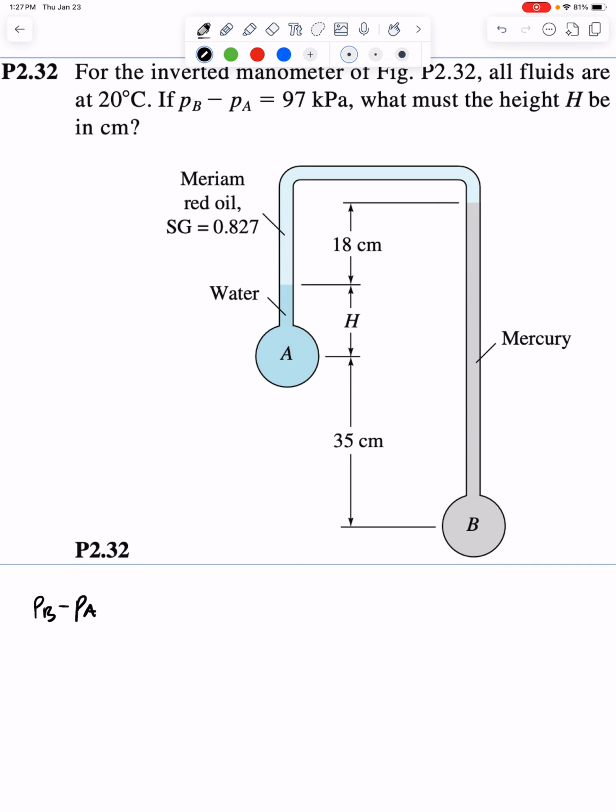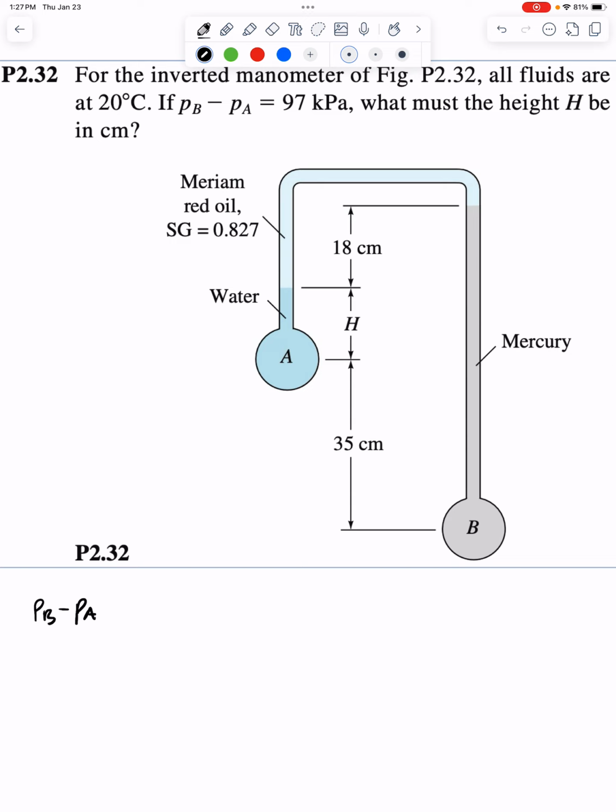So therefore, we got to change the way we think. When we do final minus initial, moving upwards means you'll get negative terms. So what does that mean? The textbook actually prefers this definition more, final minus initial. It's because when you move upwards through a fluid column, you're experiencing a decrease in pressure. At the top surface of the ocean, it's just atmospheric pressure. Moving downwards through the ocean, you experience more pressure. I think every 10 meters you travel through the ocean, that's an entire atmosphere being added above you. So moving downwards, you see an increase in pressure, so it's positive. Moving upwards, you see a decrease in pressure, which is negative. So it flips.